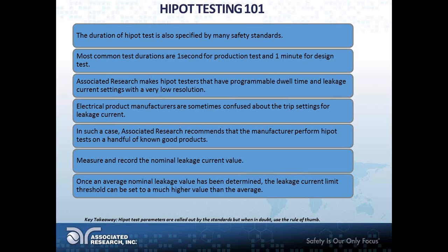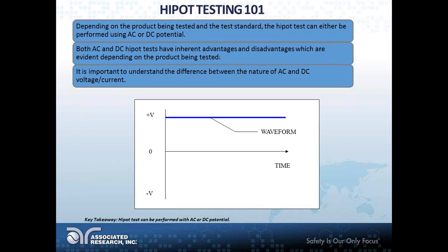And once again, the important thing to know is that the Hipot test parameters are mostly called out by the standards, but whenever you're in doubt, you use a rule of thumb for setting the voltage and the failure limits for the current. All right.